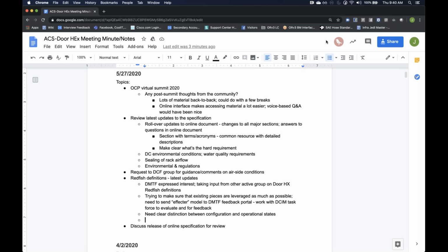We're actually coming up with virtual sensors, which is another thing that we talked about. So if you wanted to do a differential temperature as the input to this, you could actually have input water temperature, output water temperature, and create a virtual differential temperature sensor. Yep. And we have some of those concepts for exactly that reason.